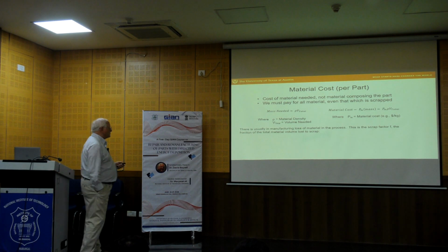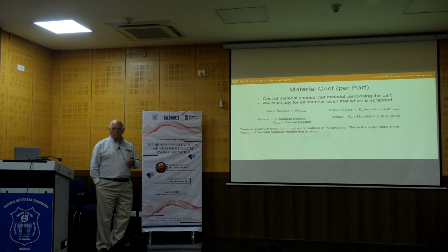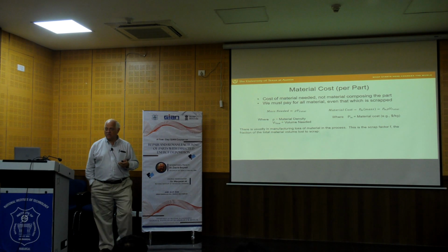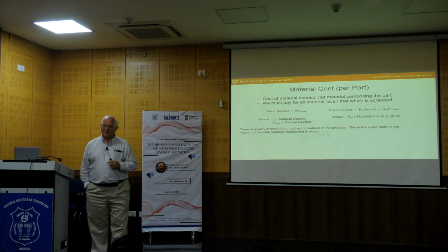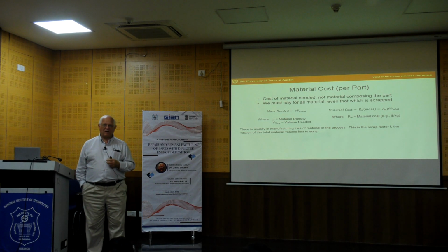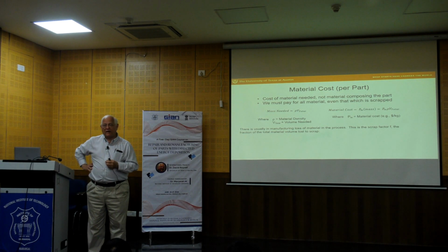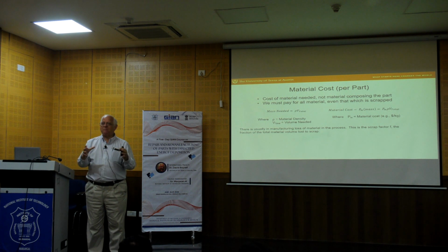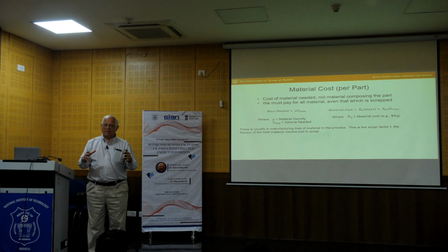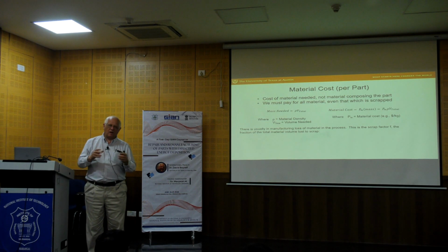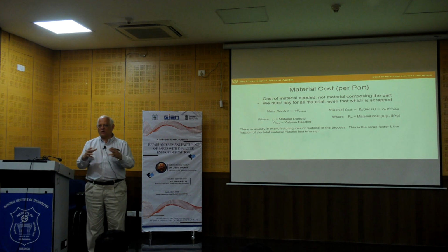Okay, so there's usually material loss, not so much in additive manufacturing, but there is some. The classic example I think of is PEEK polymer in powder bed. PEEK is a very expensive polymer, and it degrades thermally very quickly, and so it can't be recycled. So if I'm doing a full chamber build with PEEK material, a typical part versus part cake ratio is typically the full chamber build.